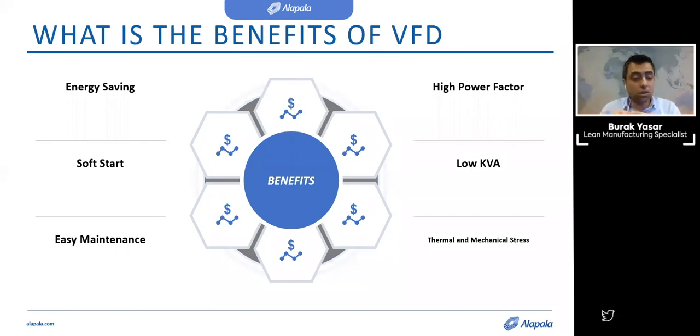All right. So, another benefit there: at the instant of energization, the locked motor current is about 600% of full load running current. This heavy current then drops off slowly as the load breaks loose and the motor comes up to speed, but it causes unacceptable voltage sag on the power system, adversely affecting other loads. It can also cause shock damage and long-term excessive wear on the motor.